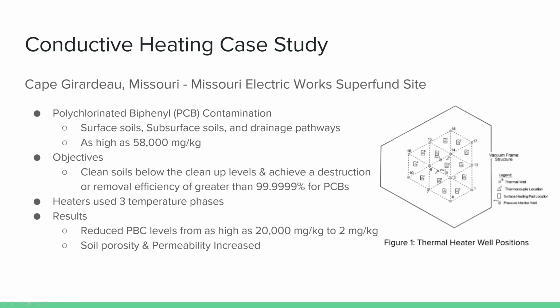It was also found that the heating process increased soil porosity from 30 to 40%, and permeability increased from 1 times 10 to the negative 3 to 30 millidarcy. This was attributed to the removal of organic matter, clay desiccation, and evaporation of in situ soil moisture.